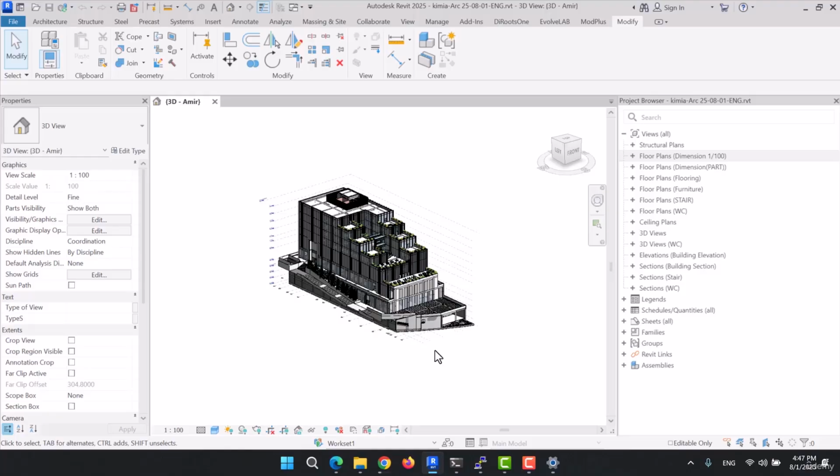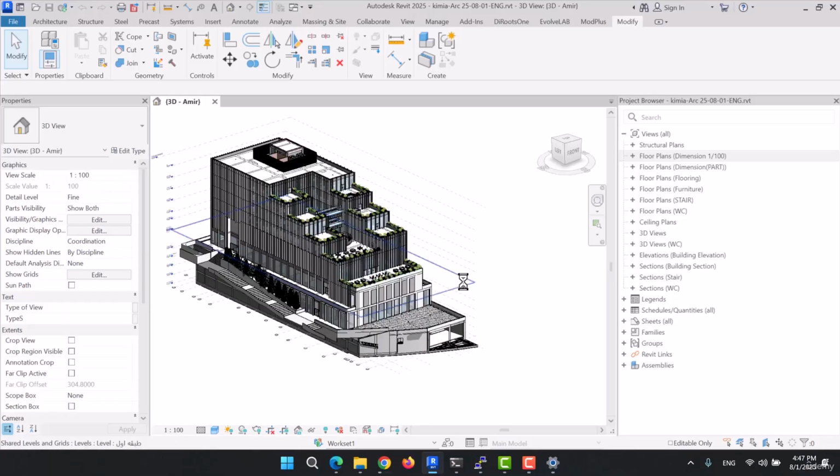The reason why you see that the scale of the countertop plans is different from those two plans is because in those two plans we do not show much information. For example, in the furniture plan, you do not need to show so much detail that you need a scale of 1 to 50. But in the countertop plan, why? Because you see the elements of the countertop, you want to make it a larger size, you want to make a tag, you show a lot of information in a large size plan. But in a flooring plan, you may not need to show that much information. In the furniture plan, you do not need to show that much information. That is why their scales are different from each other.